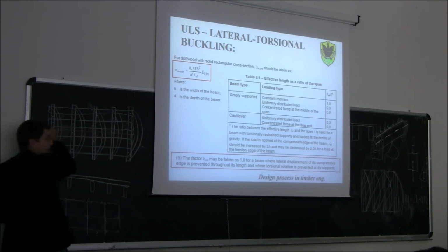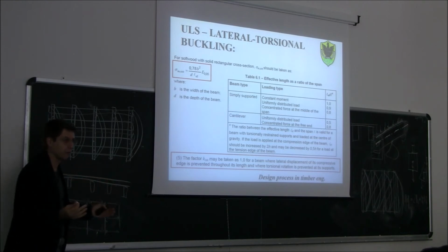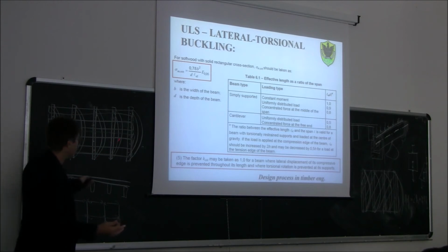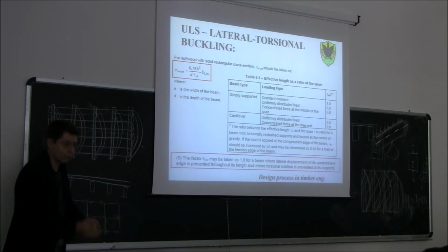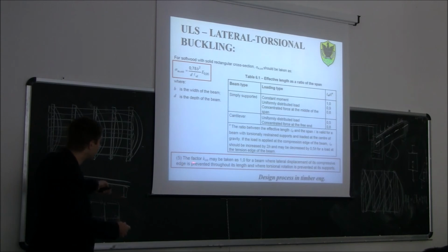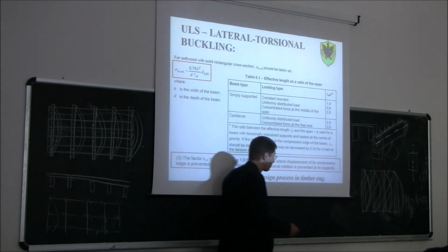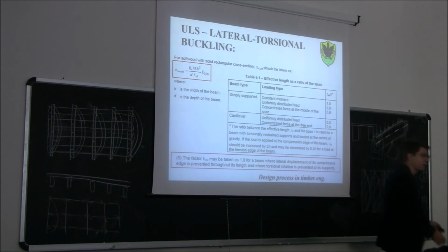If you have a very wide panel, then to get this displacement, the panel should distort in shear. So you should have a shear distortion of the panel, which is very difficult to have. Okay? So remember that the way to strengthen the floor is actually to have a layer of boards, not only one layer, but two or three layers, or to use some two-dimensional panel. In this case, you can say this panel prevents the displacement of the compression edge of the beam. Or, of course, if you have reinforced concrete, even better.